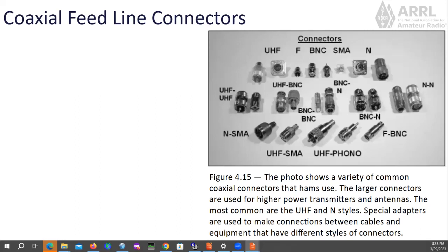The one that you see on most of your portable radios now is a, sitting here looking at one. Harry, tell me. The connector on your handheld radios, however, there are two types of those that are common. If you have a Chinese radio, the one that's attached to the radio is a male connector, and it's an SMA male.